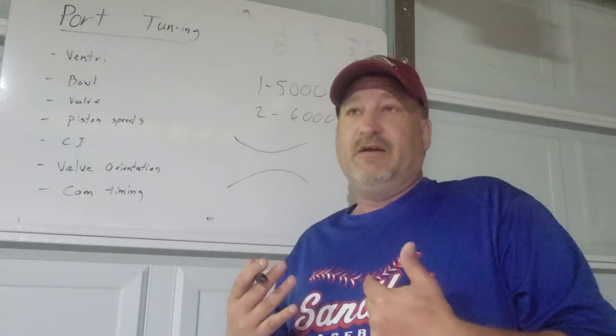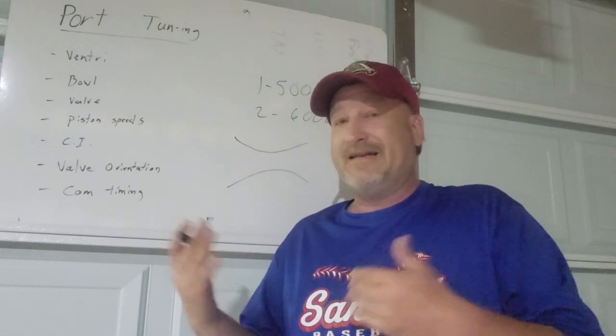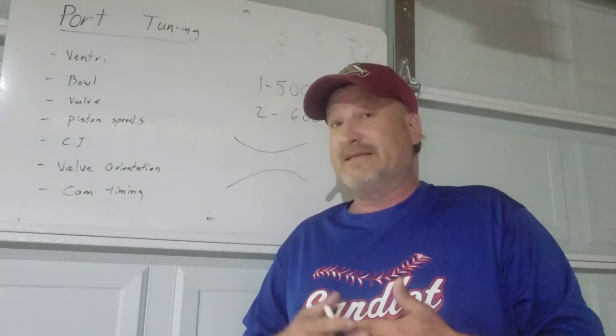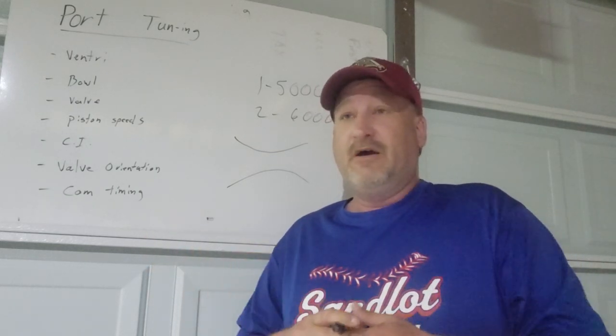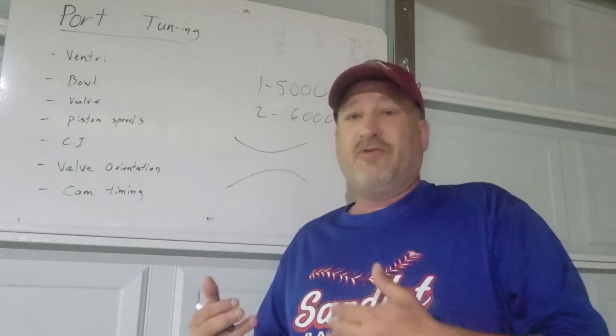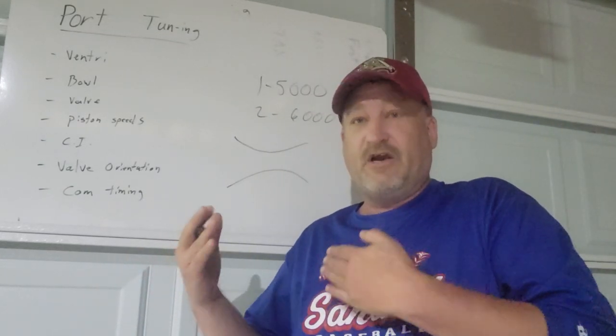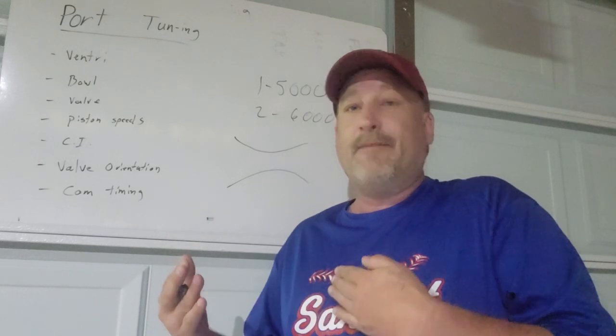Small block Chevy, you go back, and even the 350 used multiple different connecting rod lengths. So whether it's the 6-inch, 5.7, or even the 5.5, obviously not exact numbers, that altered piston speeds directed towards the specific RPM that the engine was designed to operate at.